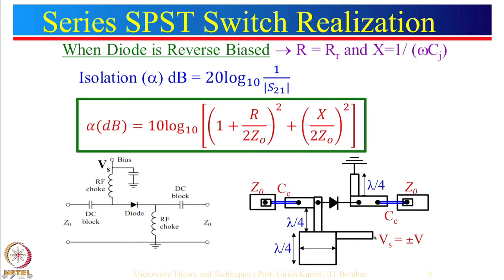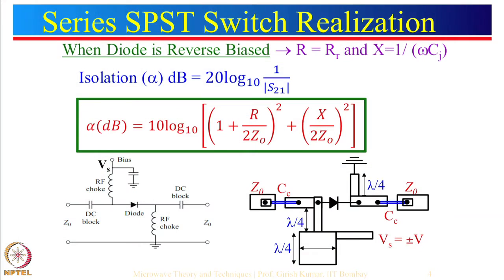So now let us see what happens here. See, a narrow strip line has been used over here, which acts as an inductor. So inductor will provide a high impedance path, Z is equal to j omega L, and for narrow line we know that the inductance will be large, hence impedance will be large. Now let us see how this capacitance is being realized. So you can see over here this particular thing acts as a patch capacitance. So we know that patch capacitance provides capacitance from the top substrate to the ground plane. So this acts as a patch substrate going from the voltage Vs to ground.